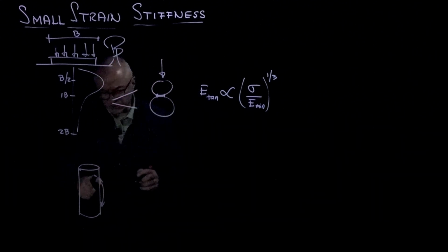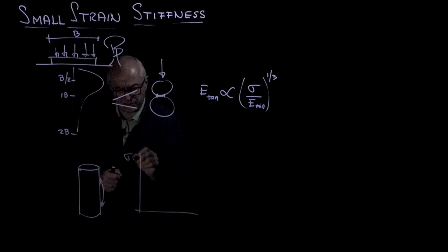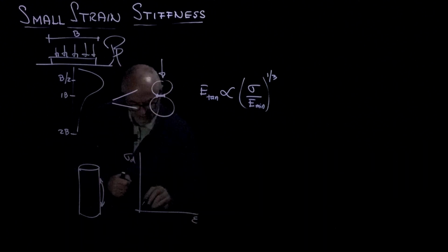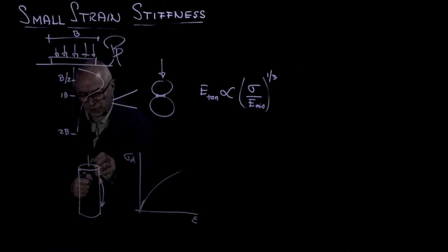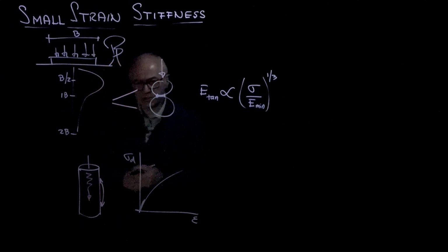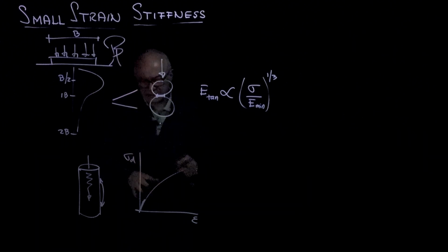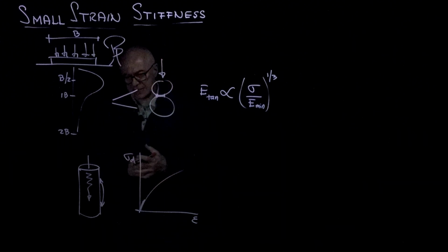And so whether we do local displacement measurements and we plot the deviatoric stress versus strain, and we see that slope, or we are sending wave propagation through the system, we should get pretty much the same modulus. In fact, they are not necessarily the same. The static and the dynamic modulus have some differences, both in soils and rocks. But we are really talking about the small strain regime, and we are looking at that parameter.